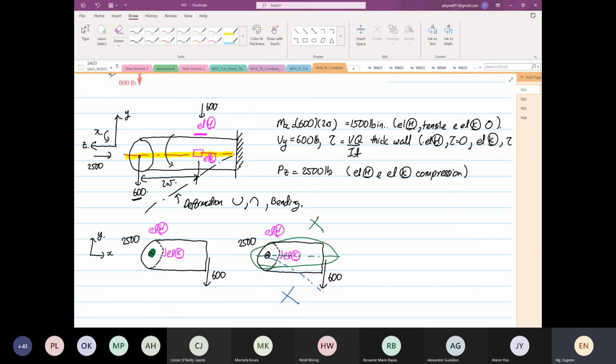And then you'll say, okay, if Eugene said it is a sad face or smiling face, this is a bending moment. Better not use acronyms. This is a bending moment. Then your answers will be all wrong. If you look at this view, the correct way, the green part that I colored is your neutral axis.